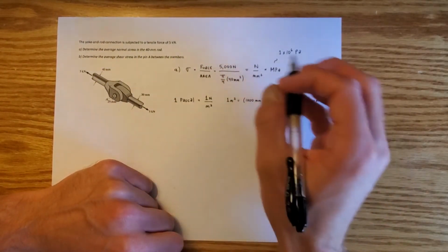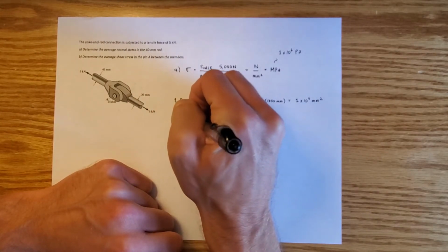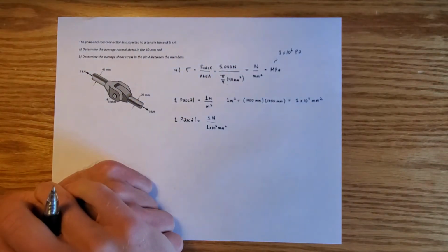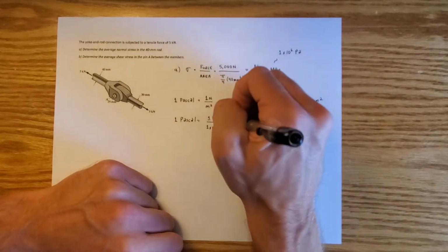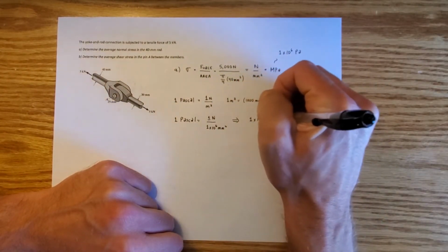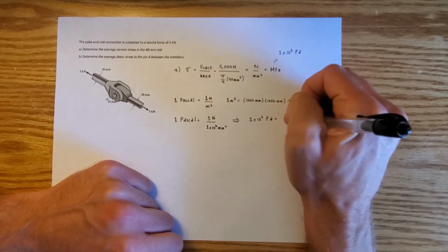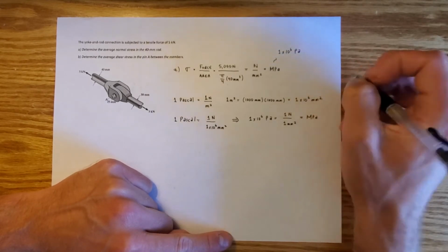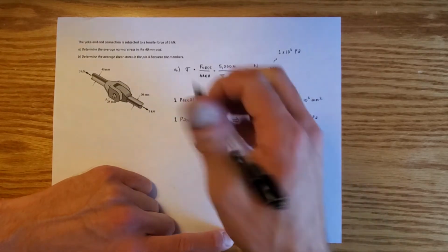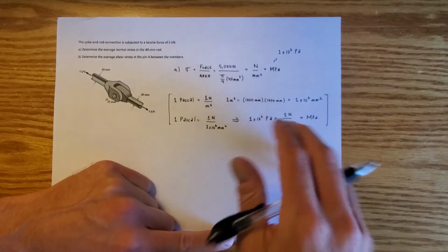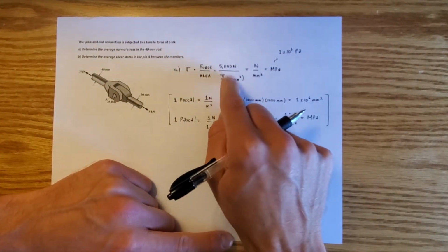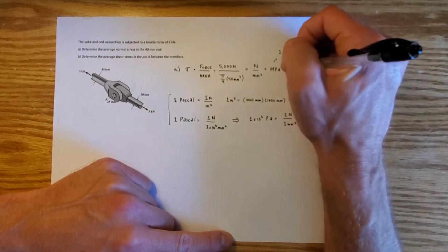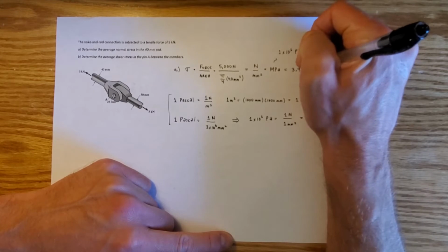So what I can do is rearrange this equation right here, and I can say that 1 pascal is equal to 1 Newton per 1 times 10 to the 6th millimeters squared. If I multiply both sides by 1 times 10 to the 6th, this becomes 1 times 10 to the 6th pascals is equal to 1 Newton per 1 millimeter squared. And that's why 1 Newton per millimeter squared gets us the units of megapascals, or 1 times 10 to the 6th pascals. This is a really good little trick that I think makes solving some of these problems a little bit easier because you don't have to convert units. Anyway, back to this part right here. We've got 5,000 newtons over pi over 4 times 40 millimeters squared. Again, we're getting this answer in megapascals. And what we get is that the normal stress is equal to 3.98 megapascals.